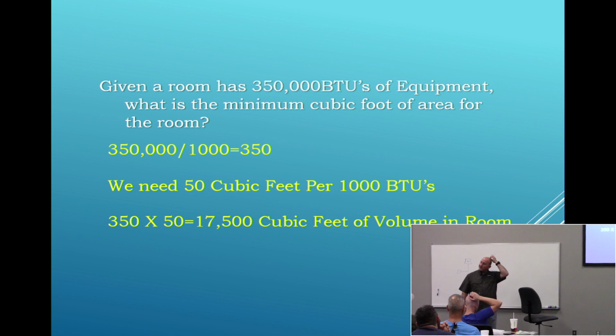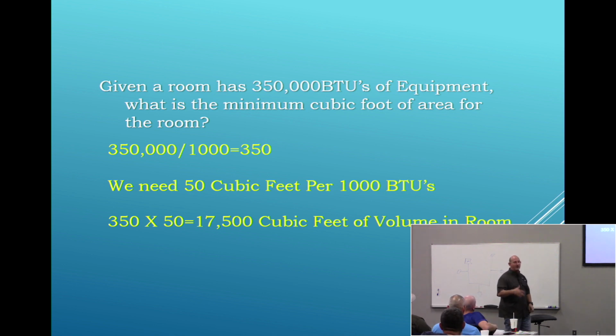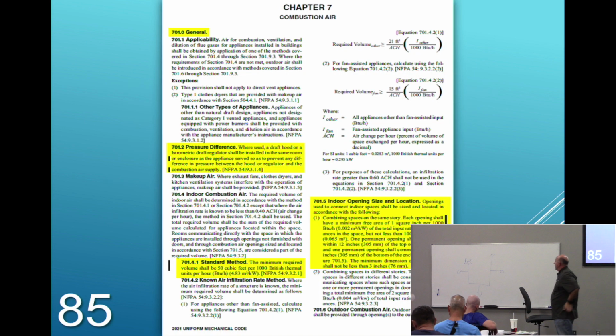So again, do we agree if the room's big enough, we're done? Move on. Don't read anything else. But if the room's not big enough, do you agree now we got to follow 701.5 or 701.6? Still not both, but either one. Agreed? Let's move on to 701.5, middle right.